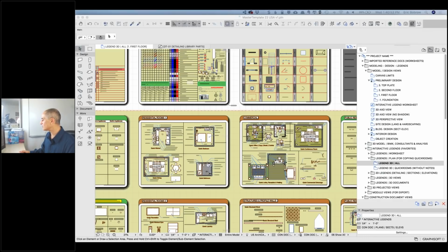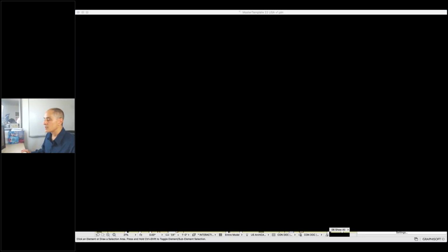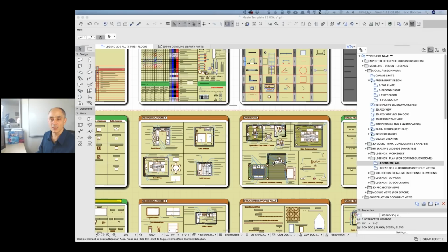All right, let me see what questions we have here. Jay says, isn't it more efficient to use the renovation filter to assign demo, existing, and new annotations than have additional layers? Yeah, just in general, I do recommend that because you then have layers for different elements, you know, walls or cabinets or furniture, and the elements have designations, so you can turn them on or off.